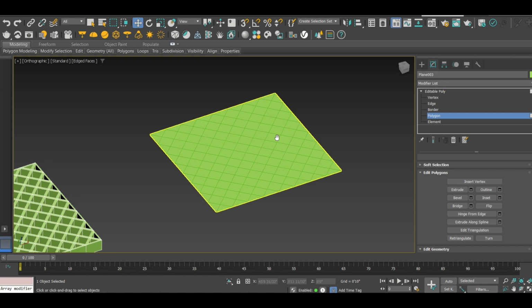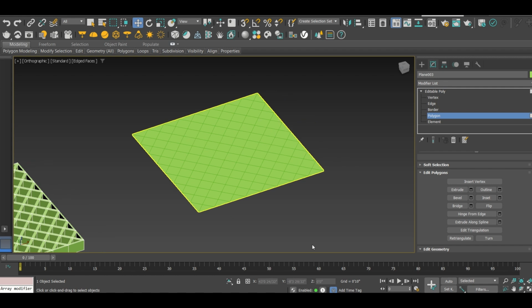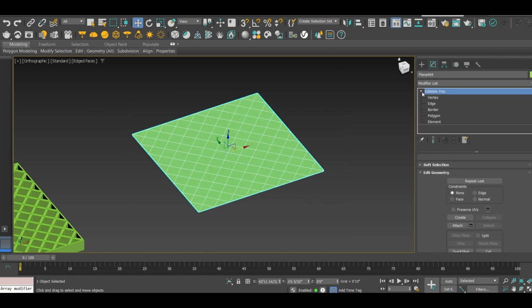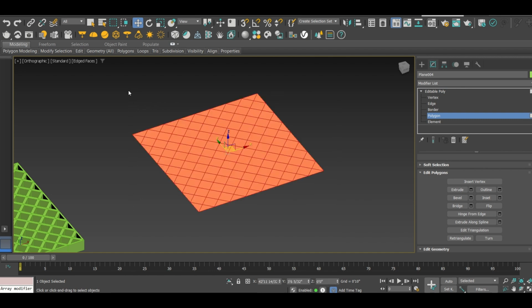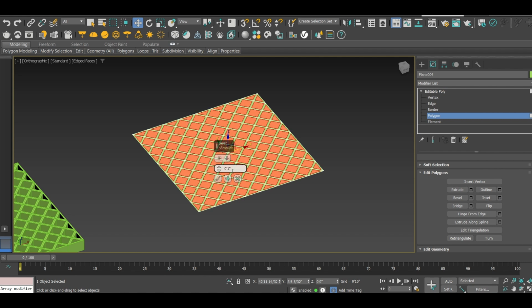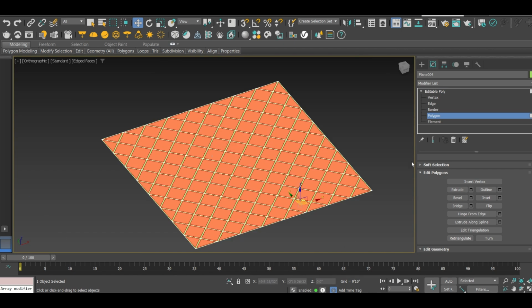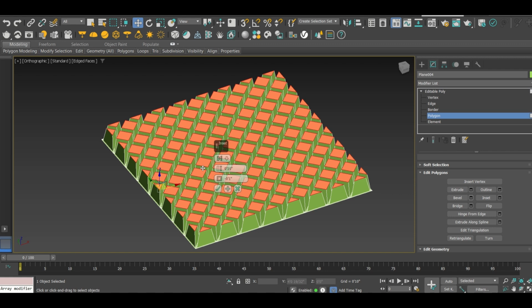In the third one, we have to use this same pattern in a different way. Going out of the command, again selecting the object, clicking onto the polygon, right? Inset command by polygon, let's say 0.5, right? So this one. Now instead of deleting these polygons, you can bevel this one using the bevel command just below the extrude, right? By polygons.